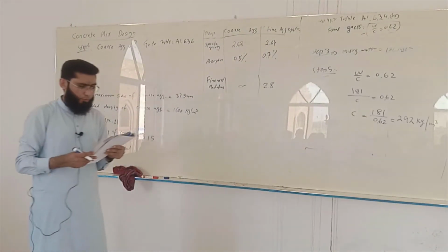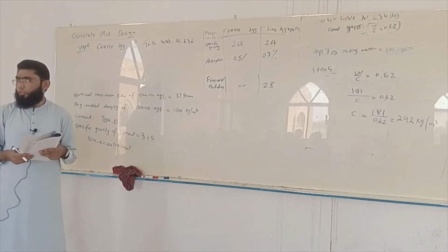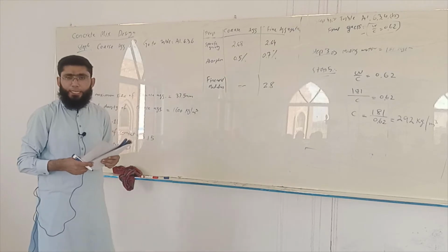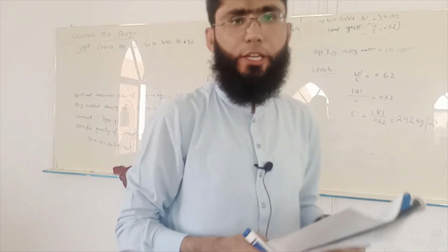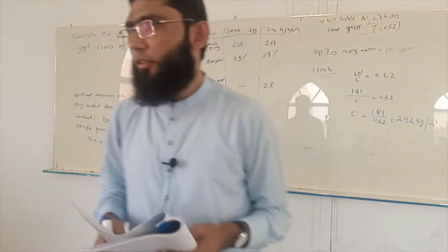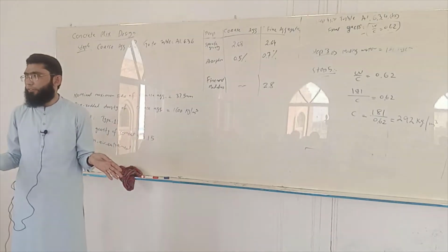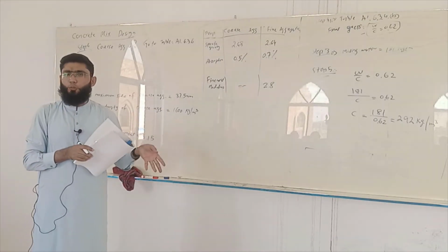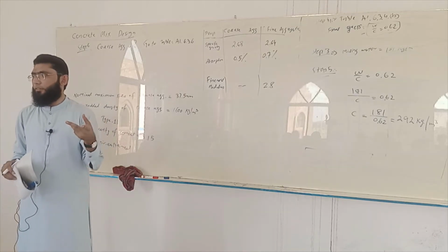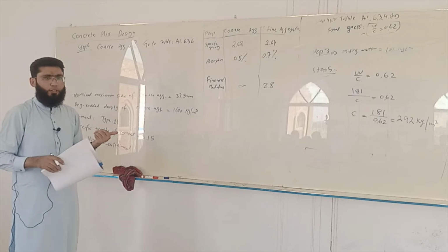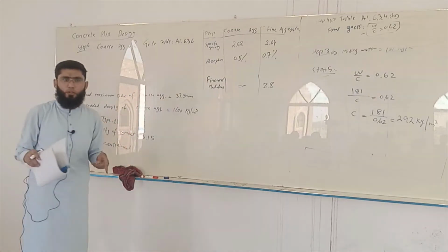On the top left of page number 23, you should be able to find table A 1.6.3.6. It says volume of coarse aggregate per unit volume of concrete. So we're not yet deciding the kgs of coarse aggregate per meter cube of concrete. First, we're going to decide the meter cube of coarse aggregate per meter cube of concrete. We can then convert using densities. We're going to decide this from this table.